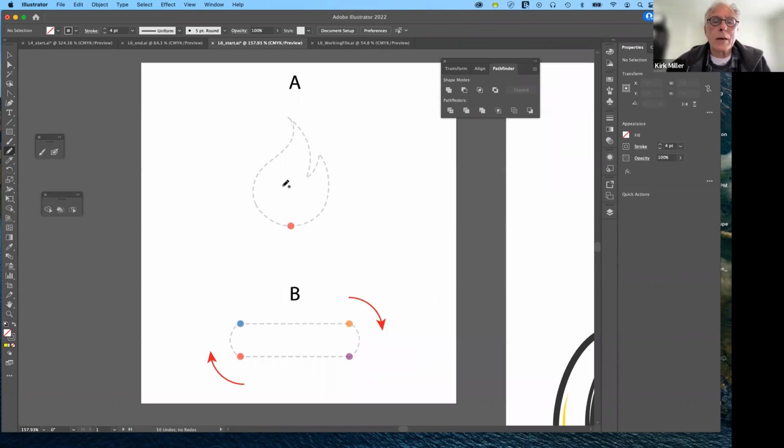I'll start by clicking here, and we're just going to hand trace this shape. Now, I would much rather, for a more accurate shape, use the curvature tool or the pen tool. But they're suggesting with the current settings that if I click here and drag slowly around, even though my hand isn't really steady, it will curve around and make things much nicer.